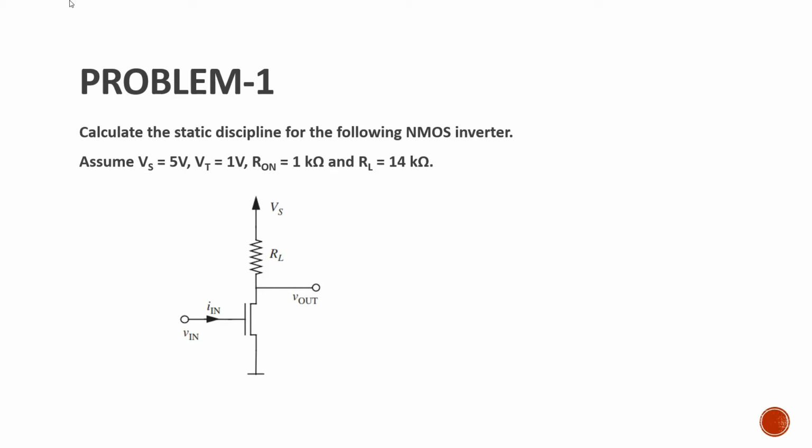Well, fine. Good. And here VT is 1 volt. Then what could be the VIH? VIH is the minimum voltage to recognize as a logic 1. What could be the VIH? Slightly greater than 1 volt. Yeah, VT plus. Similarly, VIL, which represents logic 0, is, yeah, honey, slightly less than 1 volt.